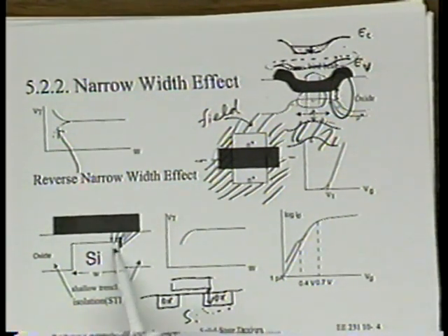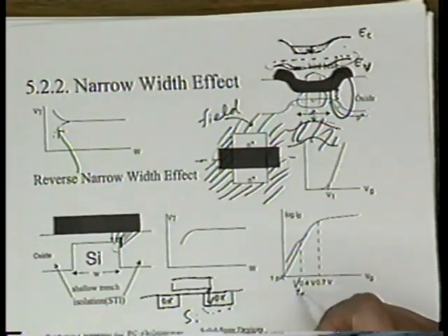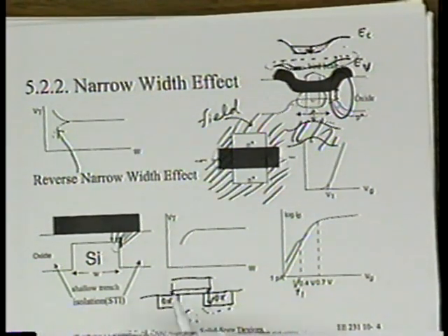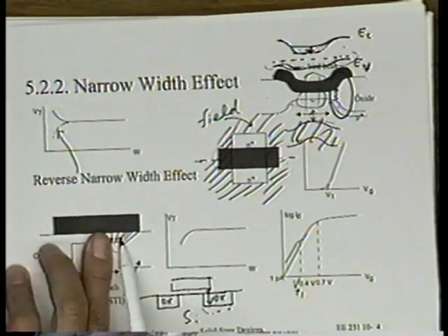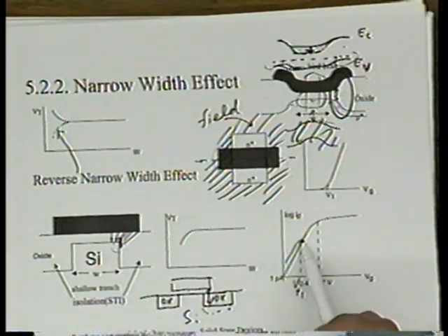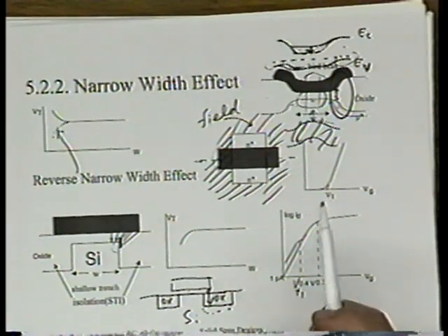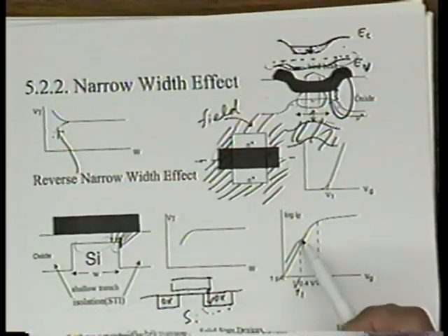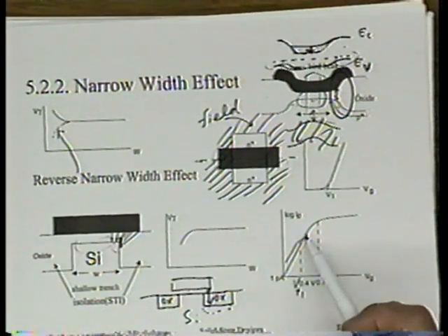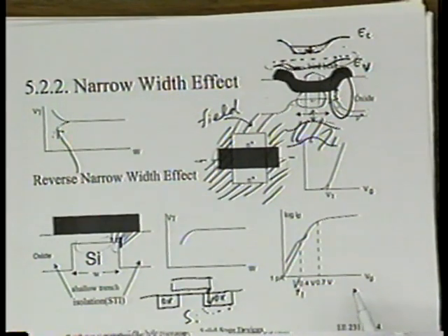Lower VT here. Because of the lower VT, the current starts to happen here, therefore it starts to happen at VT1, let's say. Right? This lower VT1. But because this transistor can conduct only very small current, given the small effective W here, just the corner, the current will saturate, maybe at only 0.1 microamp or something like that. Whereas the main transistor continues to stay in the subthreshold region until we reach the VT of the main transistor, for example. So you can have a situation like that.